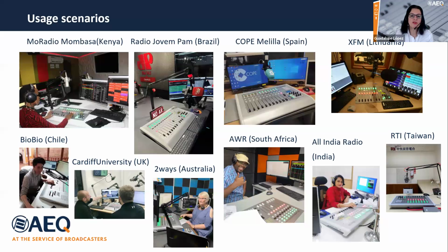How can we have more than 4 microphones in the Capitol? Typical question. As I said before, the M core, the engine, comes with 4 inputs. But using a Dante interface with the Dante option in the M core, you can expand up to 32 microphone inputs. That is a very cool advantage that we have with the Dante option, that we can integrate Dante interfaces in order to expand input and output for the Capitol.